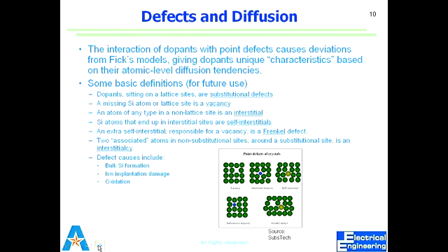Defects will be places where there is a need for a charge to come in and fill up, to satisfy the 4 bonds around it. So those will be electrical sinks. They would hinder the flow of charge. So that reduces mobility.